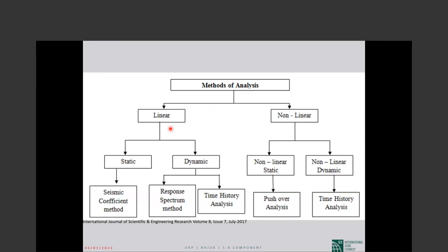So our story there finishes this way: in the elastic, in the linear approach, we have m values for deformation control actions. The only thing that I should remind is that for the deformation control actions, when we want to calculate the capacity, again the same formulas as the new building codes are used.